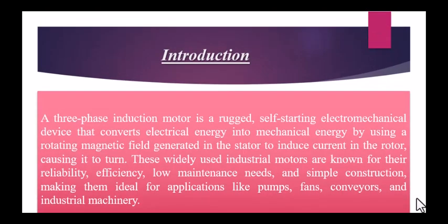A three-phase induction motor is a rugged, self-starting electromechanical device that converts electrical energy into mechanical energy by using the rotating magnetic field generated in the stator to induce current in the rotor, causing it to turn. These widely used industrial motors are known for their reliability, efficiency, low maintenance needs, and simple construction, making them ideal for applications like pumps, fans, conveyors, and industrial machinery.